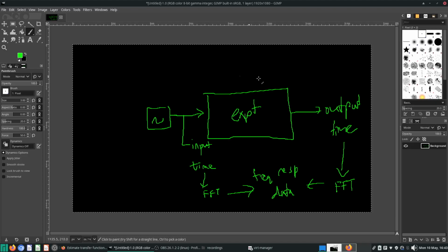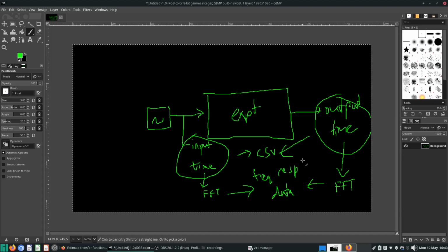So you want to test this kind of a setup here in LabView, and get familiar with some of the stuff, how to do it, especially how to eventually later on export all of this, at least the input versus time and the output versus time, to some CSV file. And after that you can probably try to use MATLAB to sort this out using some of their functions, but as of now I'm just interested in generating a CSV file with input versus time and output versus time. That's all. That's what I'm trying to do here.